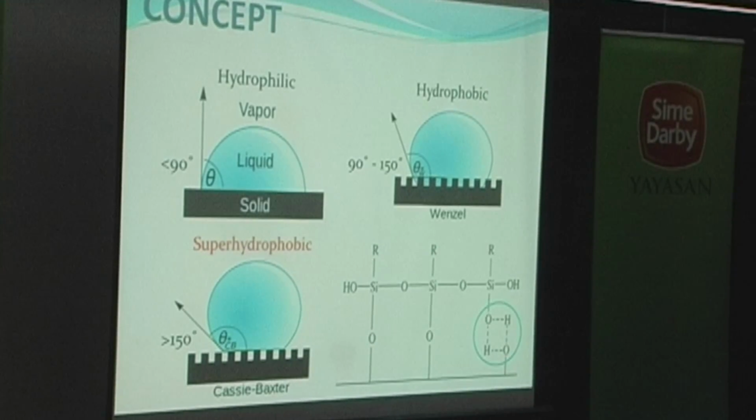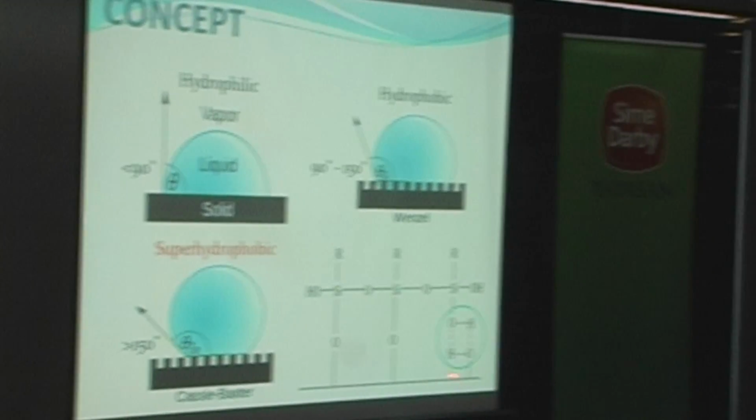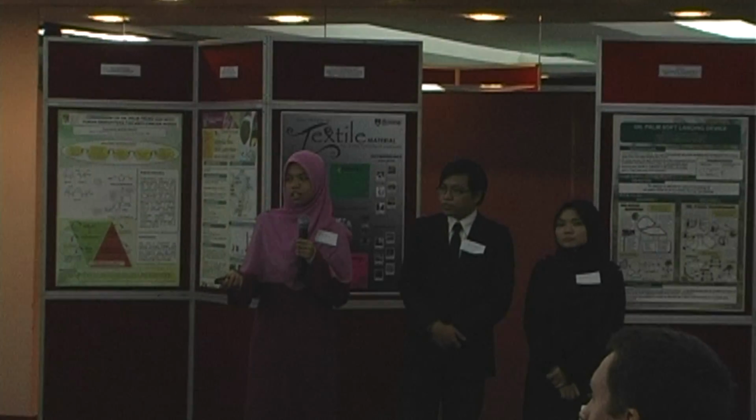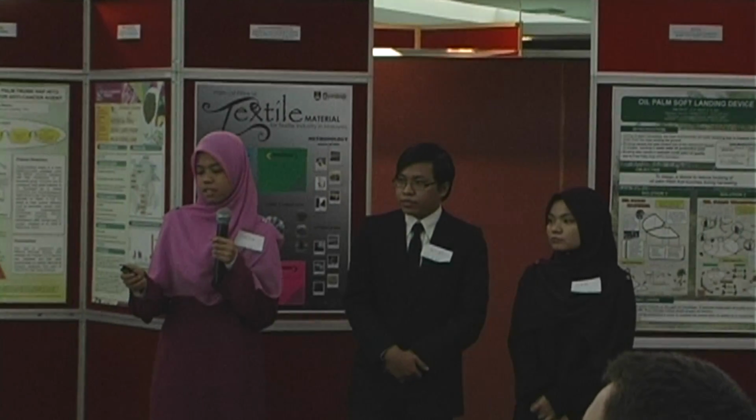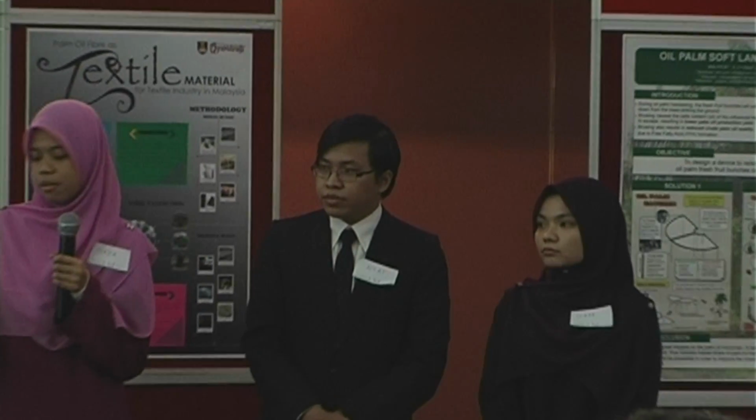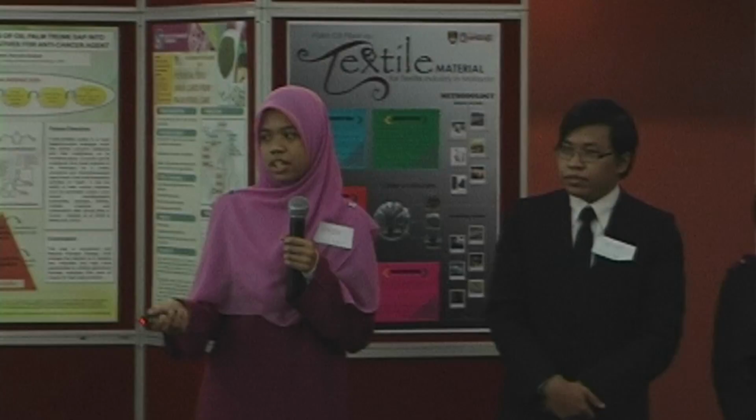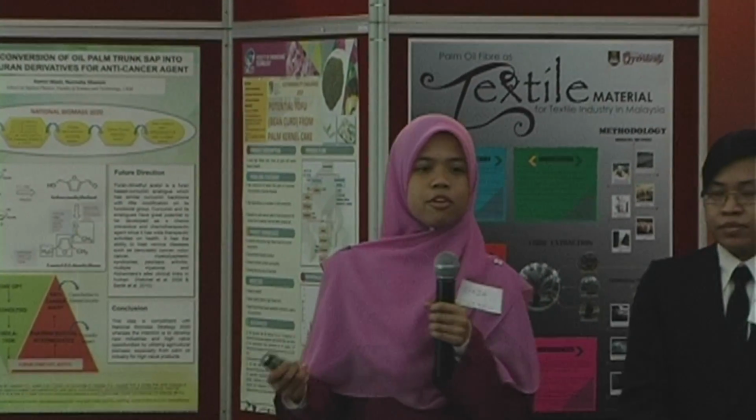A super hydrophobic condition occurs because the ash particles have OH sites that can provide chemical grafting and roughness on the surface. So there will be spaces of air to avoid contact between the surface and the water droplet. Moreover, this is our desired outcome. Hence, we can say that through modification of the silane and the agricultural ash, we can obtain a super hydrophobic surface.